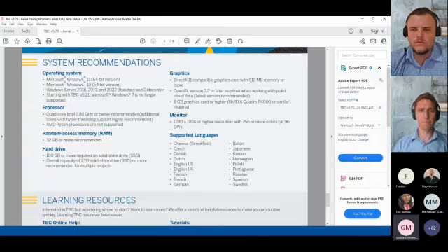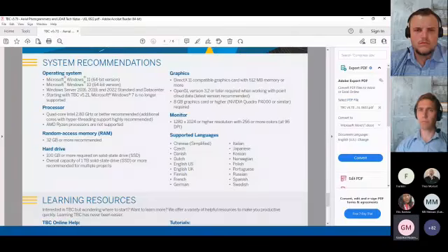Okay, thank you. I wanted to ask, when you use this type of drone after processing your data, I had an experience with one of the models, not DJI, but I wanted to ask if you compare your DTM from the drone after processing, with the points you pick, let's say you pick common features, maybe break lines or maybe tower points, whatsoever it is, and compare the elevations. How were they in relation to the data which you got from the drone? The one you get with the DGPS.